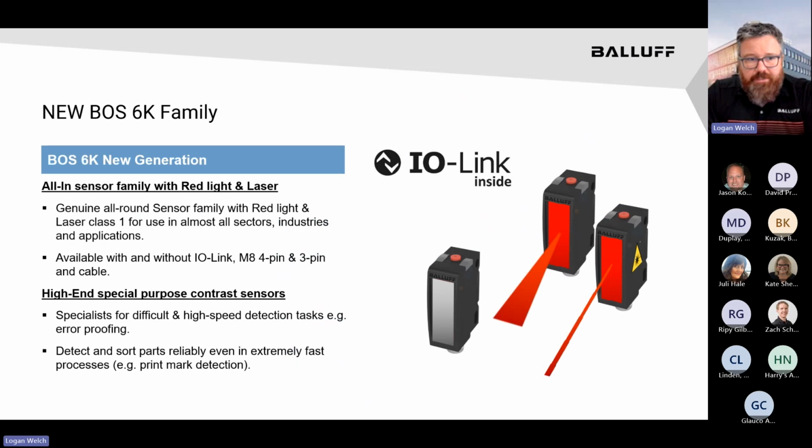Okay, so real quick, again, this is just a look at the 6K, but one thing I didn't touch on when I looked at all those technologies is IO-Link. And not to dig too deep into IO-Link, but that's just kind of where the industry's going. Some of you may be familiar with it, some may not, but this is just a great way for ease of programming, setup of sensors, a network type system into your PLC, wherever your control system is, pulling data and setup and diagnostic features from the sensor. So all of these models, in one way, shape, or form anyway, have IO-Link inside.